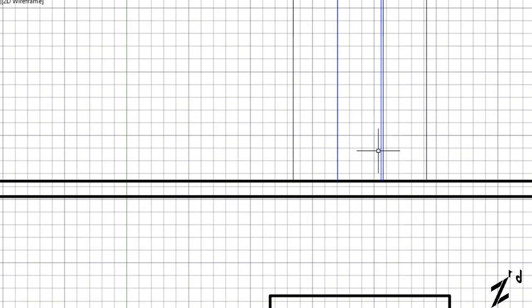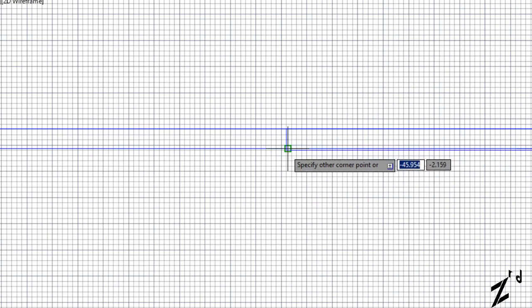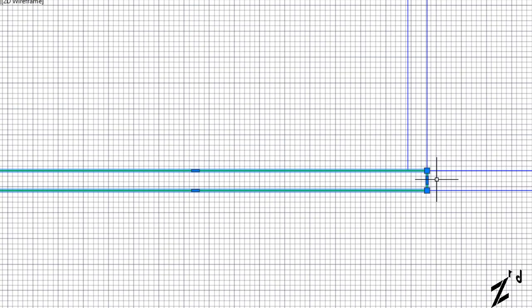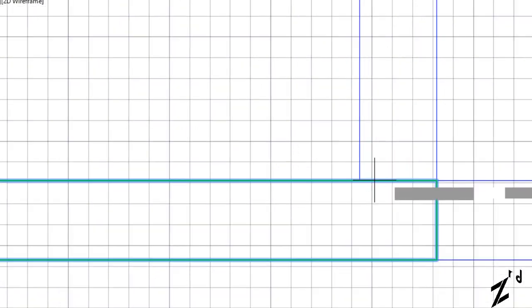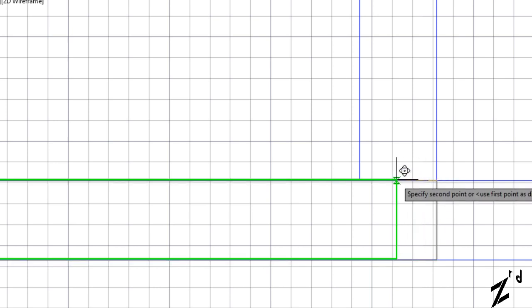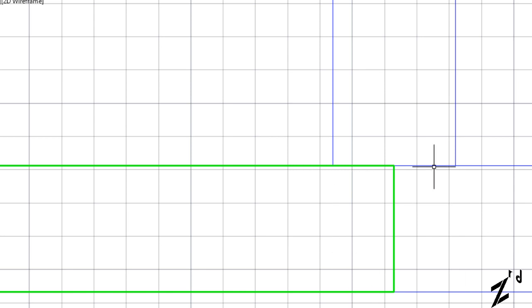Now to talk about this frame in the center. If we try doing the same full overlay thing here, let's say we start here, obviously move it there. Let's color this also green for the time being. If this door is placed like this, what happens to this door, right? That's going to be a problem. So what we need to do is share the partition. What we do here is move it to exactly halfway. So 0.95, F8, enter. Yeah, so that stays there.